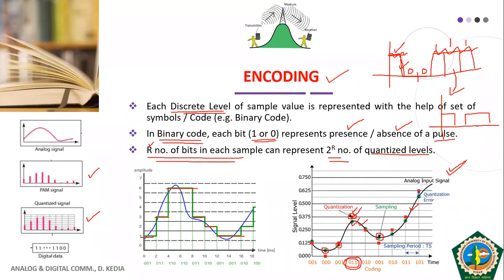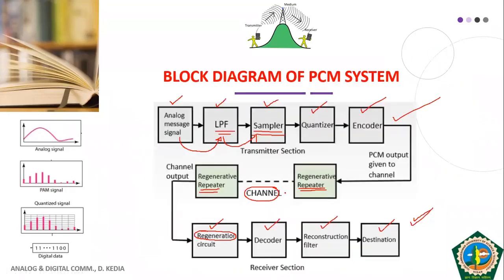The repeater reshapes and cleans up my pulses. So after passing through the repeater, my signal becomes fresh. The noise that had crept in is removed and a fresh copy of the signal is transmitted. That is the job of the repeater, which we could not use in an analog communication system, because once noise entered there, it could not be removed.